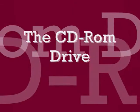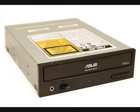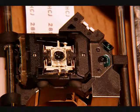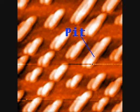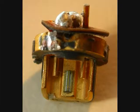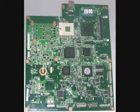CD-ROM disks are optical storage devices commonly used by PC users to load software, watch movies, listen to music, and much more. In order for the computer to access data on a CD, it requires a CD-ROM drive. The CD-ROM drive reads information off a disk by using a laser. The laser is designed to reflect off the CD and into a photodetector. While you may not be able to see it, a CD actually has tiny pits carved into it. When the laser hits a pit, its path is disrupted and it misses its sensor. The pattern of sensor hits and misses can be decoded by the microprocessor and sent as usable data to other PC components. In binary code, each sensor hit is a 1 and each miss is a 0.